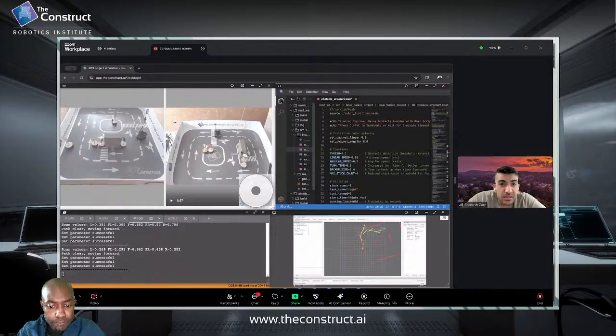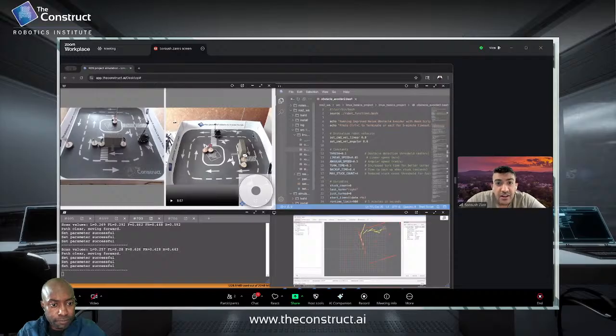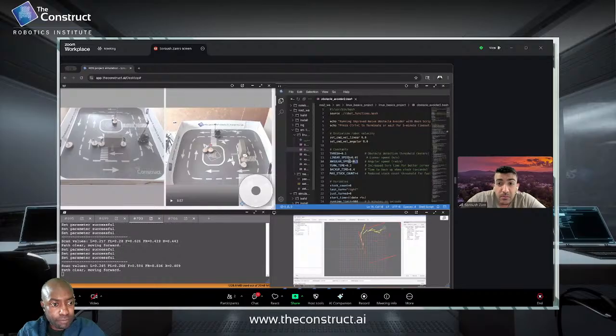And also because sometimes it's going to go to this corner and it's going to just turn around a lot and it's kind of stuck there. So I started to limit the angular speed to 0.5, and it's just going to turn for a time of 0.3 seconds. So it's just going to turn a little bit, like 90 degrees. I calculated this one by trial and error to see what angular speed with what amount of time gets it to 90 degrees.